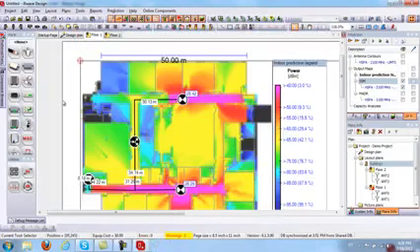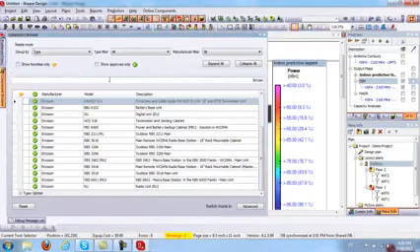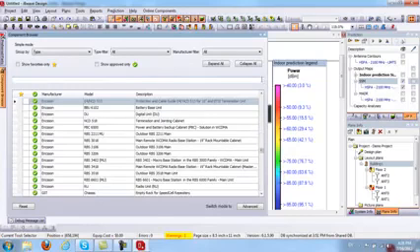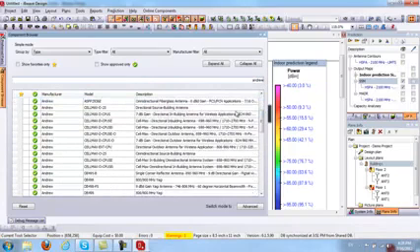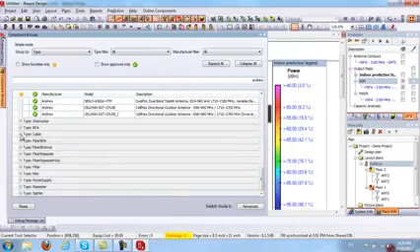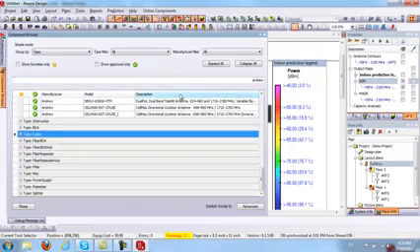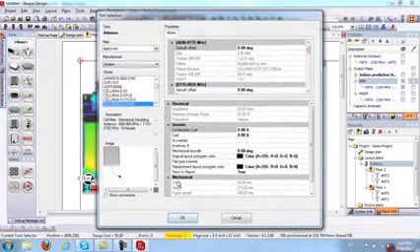The last thing again I want to mention here is your component browser. You can click on your component browser, and let's say I am looking for specific components. I can just type what I want in here. So I can type, for example, Andrew, and it will pull all the Andrew components here. I can search through the descriptions here very easily. I can look through all the antennas, BDAs, cables, and so on that this manufacturer produces. Or I can search by just about anything I want, and I can find my component. Once I want this component, I can simply click on it, and it opens the properties for it, and I can just click OK and use it.